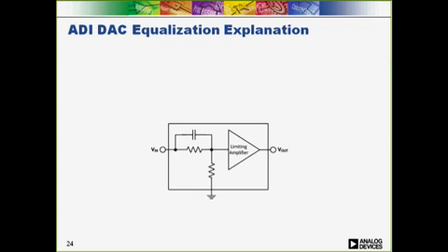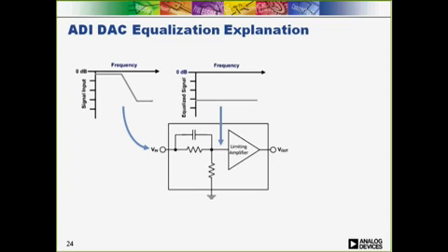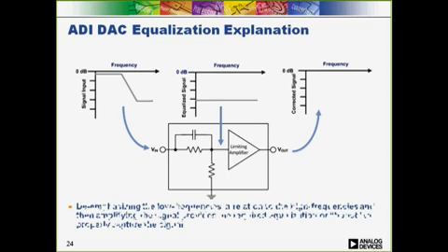Here is an equivalent circuit diagram illustrating the passive EQ used in our JESD204B receiver. The signal coming out of the channel and into the EQ has had its high-frequency content attenuated by the channel. The high-pass transfer function of the equalizer flattens the response. At this point, the signal passes through a limiting amplifier in order for the sampling circuit to accurately capture the samples.